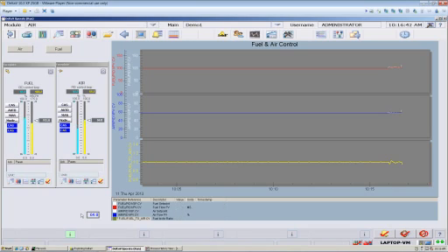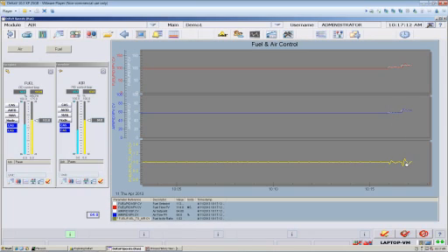One of the things I want to point out about this uncoordinated, unplanned Ziegler-Nichols method is the bigger the change you make, or the more rapid change you make, the worse this problem down here in the ratio is going to become. We both, fuel and air, responded quickly to set point, but they didn't go to set point quickly. They kind of shot past set point quickly. And the problem is air got there much sooner than fuel, so my ratio is much worse.